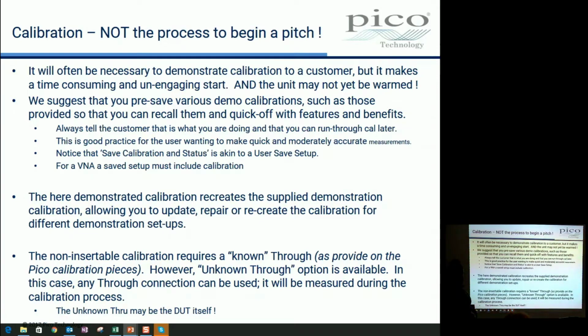It'll often be necessary to demonstrate the calibration to a customer, but it makes a time-consuming start, and the unit is not yet warmed. That's a really bad idea. You really do have about 20 minutes. It's not an hour to warm these things up, but about 20 minutes. And you can demonstrate the user interface and make some demo measurements before, and have a nice warm instrument to do your cal if you have to. Always tell the customer that that is what you're going to do, that you're recalling a calibration that you did earlier, or that Paul did earlier, and that you'll do a calibration later on.